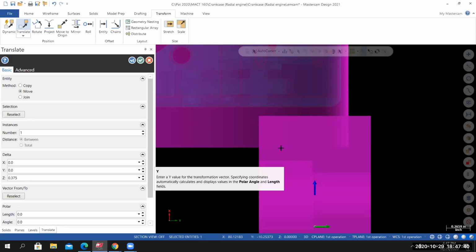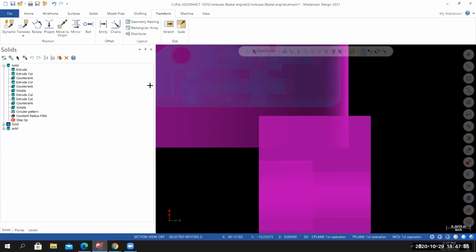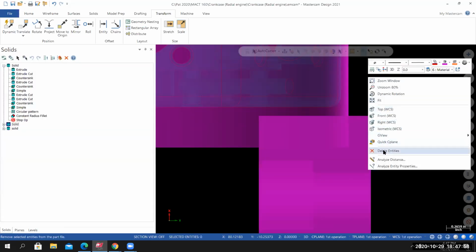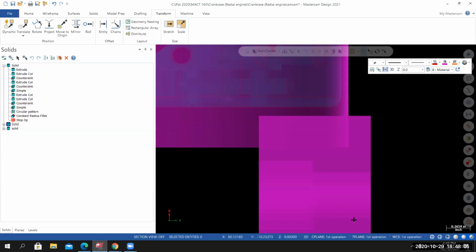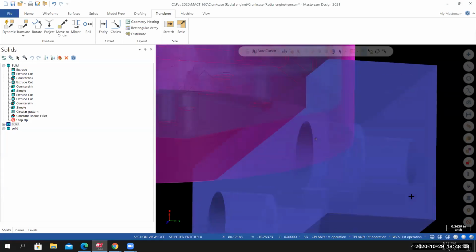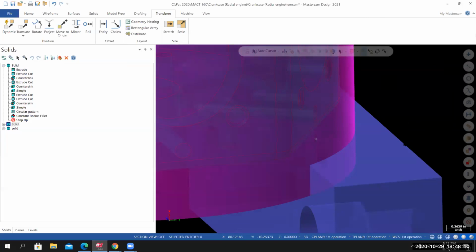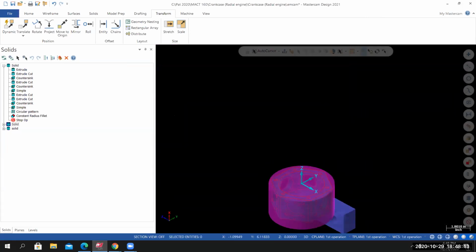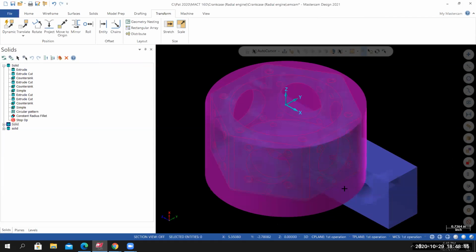I still have clearance between the bottom of the part and the counterbore. And you can see that the bottom of the material and the counterbore, I have clearance. And then the part is still above the soft jaw. I'll select OK. Right click, clear colors. Right click, isometric. Right click, fit. How's everyone doing?